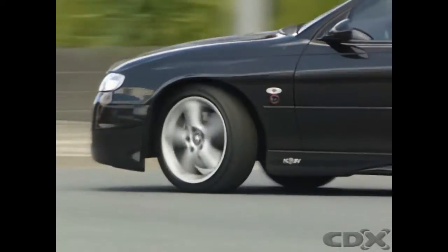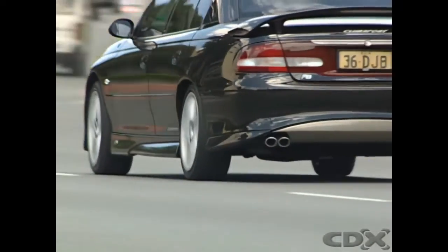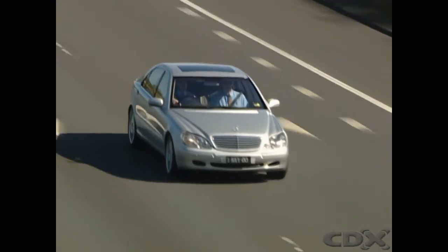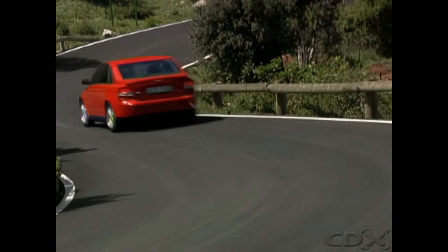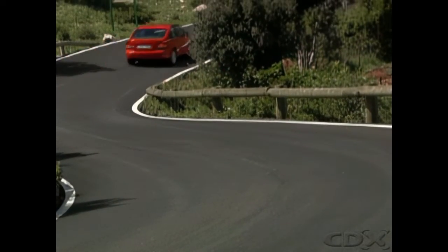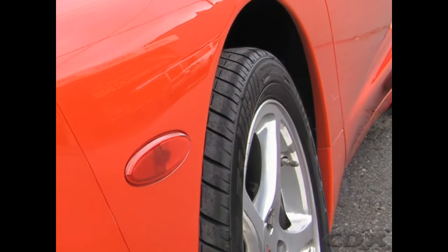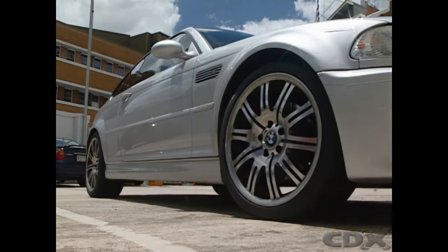Since no one vehicle will be subjected to exactly the same surfaces and at the same speeds as the controlled conditions, the number can only be an indicator of expected tread life in normal conditions. The rating is based on a percentage of the projected wear life. For instance, a tire rated at 400 has a projected life twice that of a tire rated at 200.